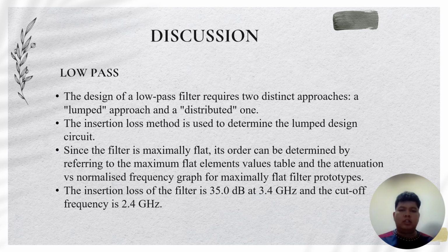Okay, this is the discussion, and this is for the low pass filter. The design of a low pass filter requires two distinct approaches, which are a lumped approach and also a distributed one. So the insertion loss method is used to determine the lumped design circuit.